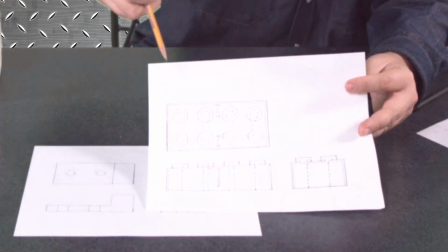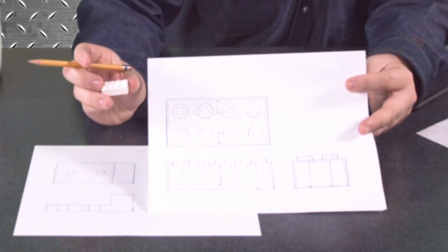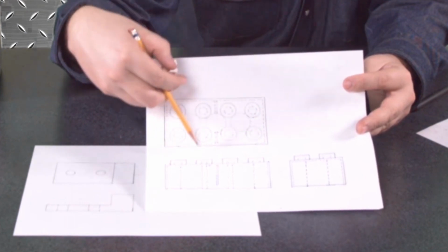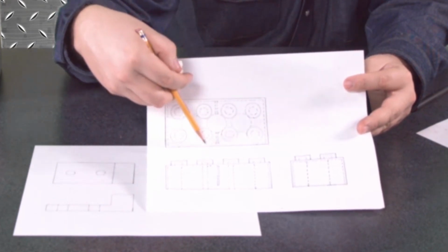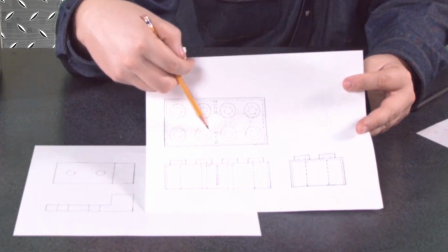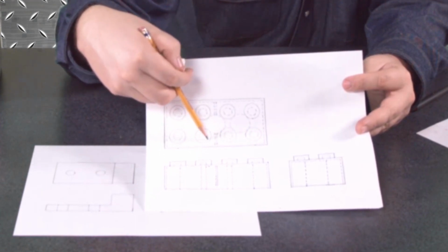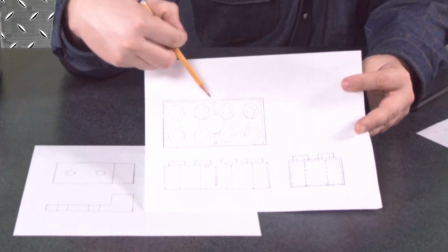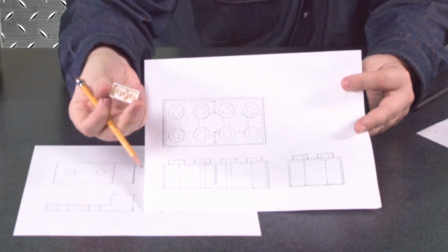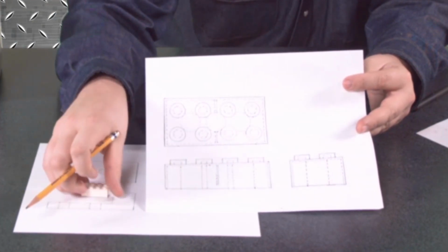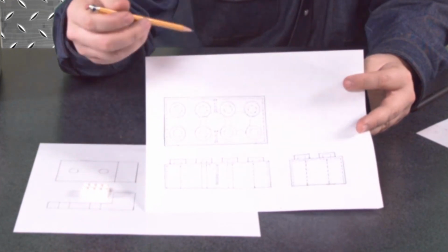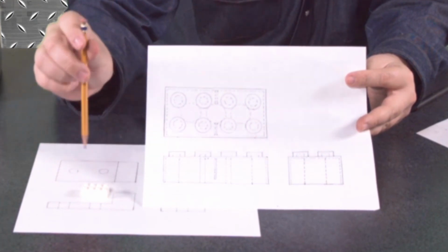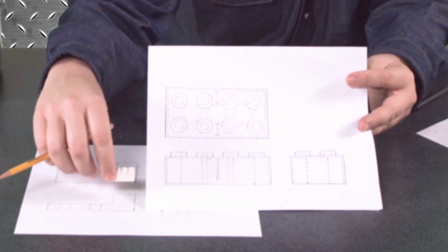the studs sticking out. And then from our top view, we can see that those internal hidden lines right there are actually those cylinders on the inside, and that these parts sticking up are round as well. And then internally, they have those other hidden lines inside of them. And then we've got 2 hidden lines here representing the support structure on the inside of this brick. And this print is just kind of to show how much more in-depth the use of object lines and hidden lines can get with even just a super simple object that we see every day.